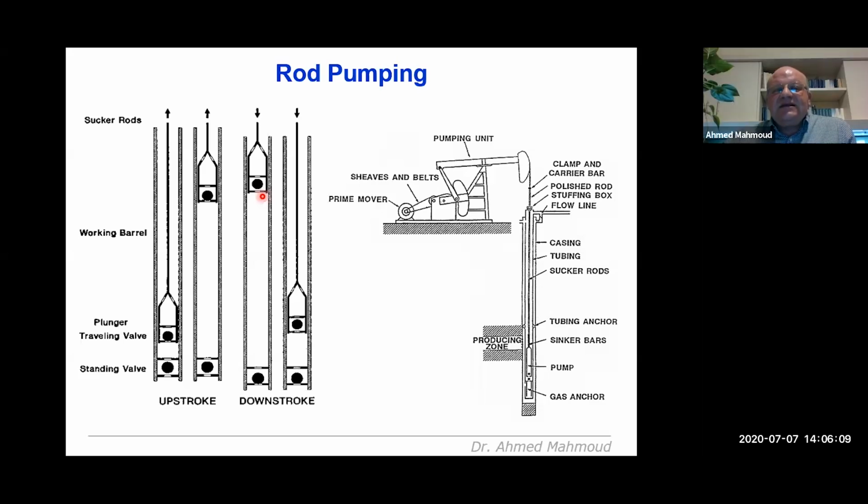But if the gas is solution gas, dissolved within the oil, it will actually help the lifting effect. It is only when the gas is separated from the oil that the oil will be heavier and act as a burden on the sucker rod system.